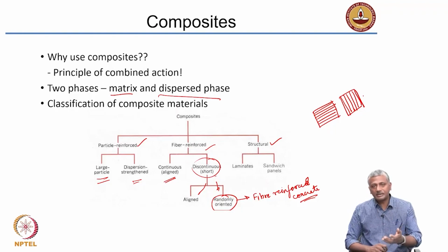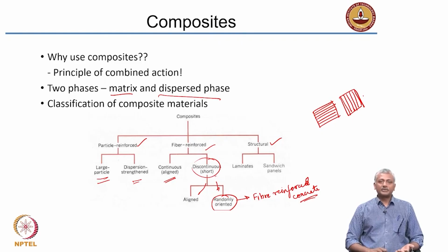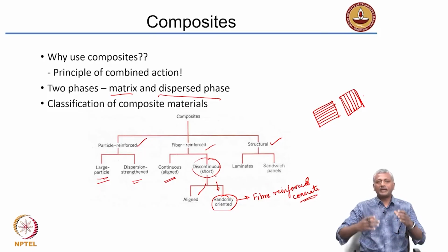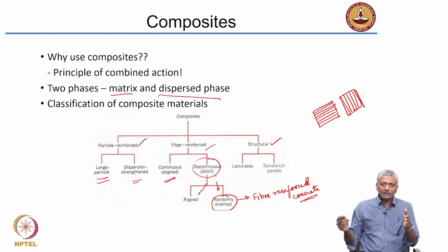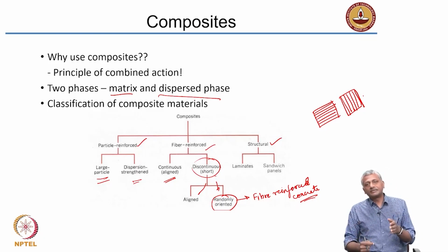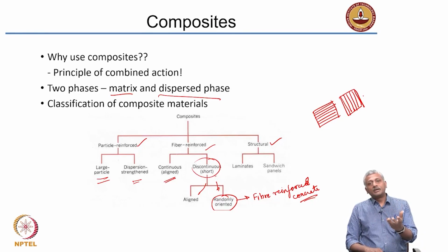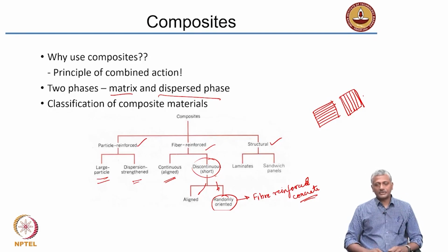Okay, so that is a part, the structural composite. Another structural composite could be a material which is a sandwich panel. So you have the exterior panels which are made of a very stiff material and an interior panel which is made of a lightweight composite. Okay, so that way your structural composite will be able to take large loads because of the exterior panels, and you do not have to waste a lot of material in the interior, and you can get some deformability and pliability because of the low stiffness material that is filled up inside. I also talked previously about the hollow steel tubes that are filled with concrete. That is also a structural composite.